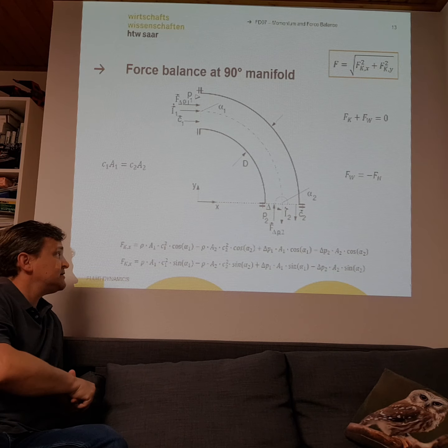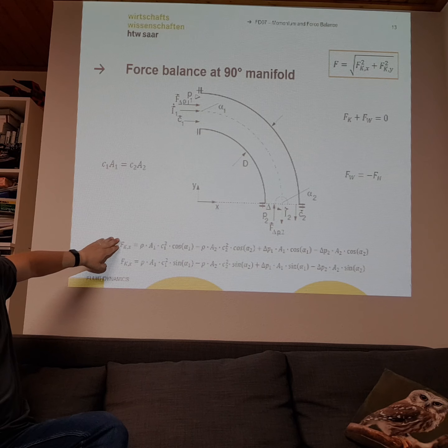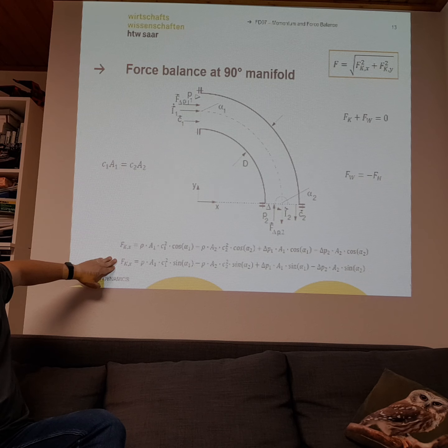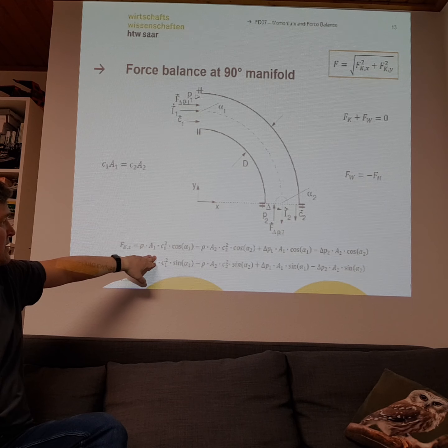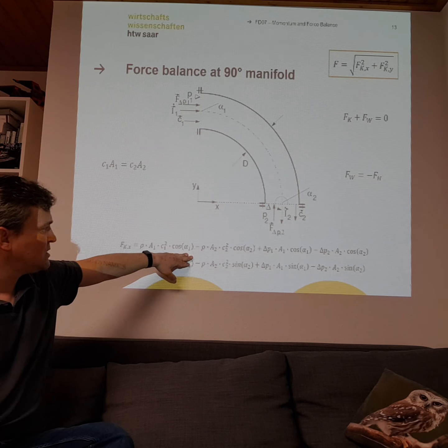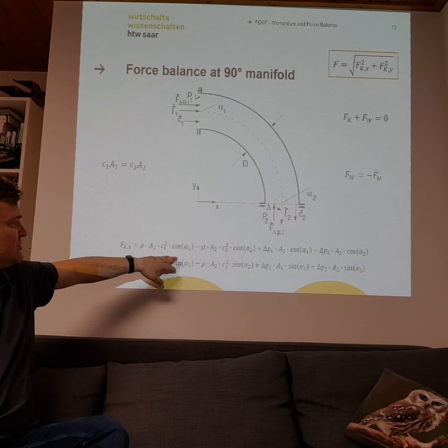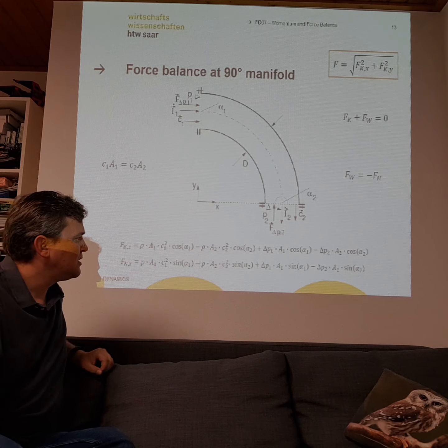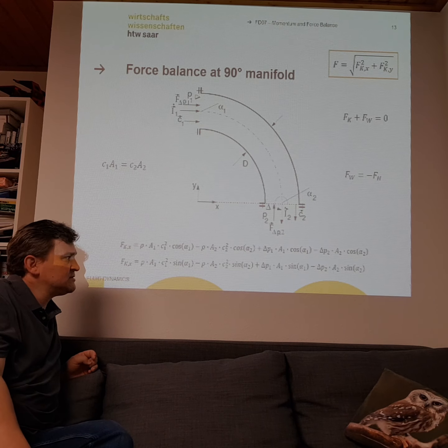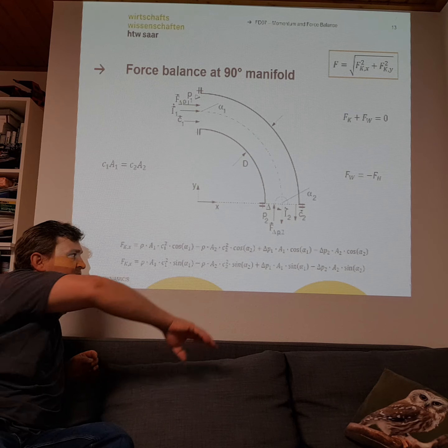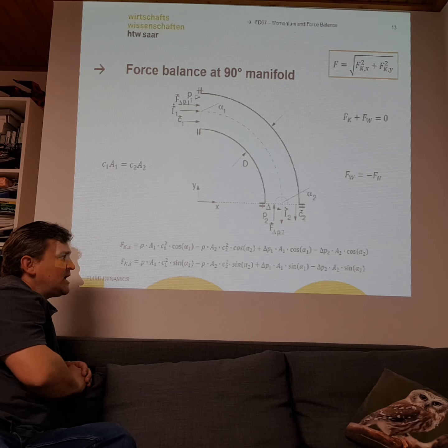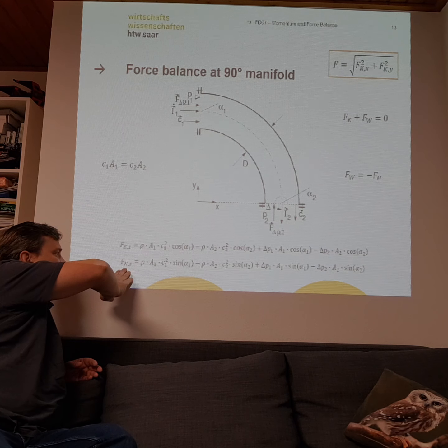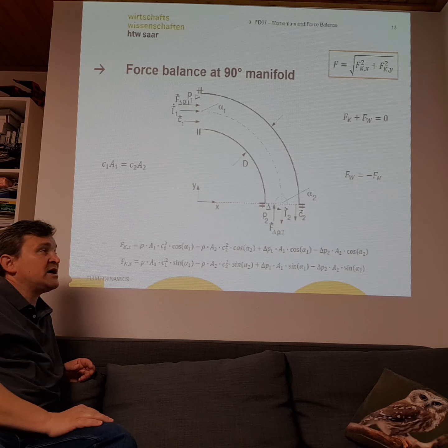Okay, and here is the definition. Again, we get a force in x direction, we get a force in y direction, we take into account the angles, we have to take into account, based on Bernoulli's law, again the momentum times cosine alpha for the force in x direction, and sine alpha depending on the force in y direction.